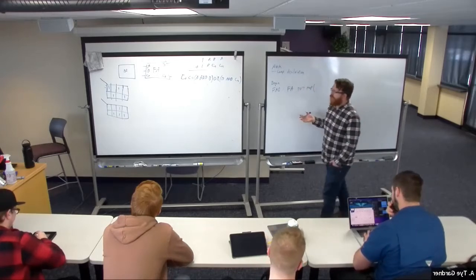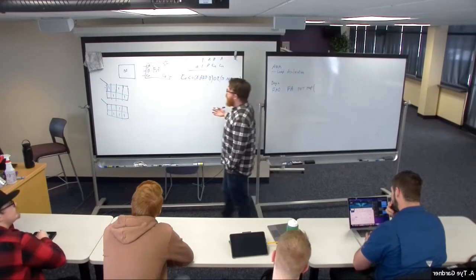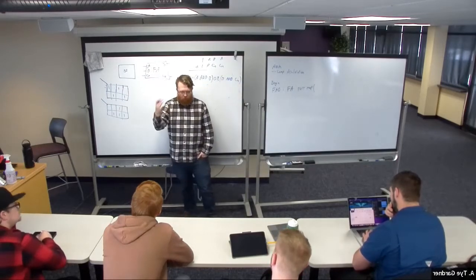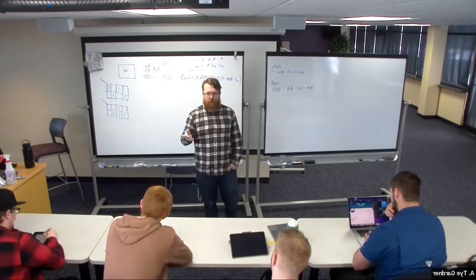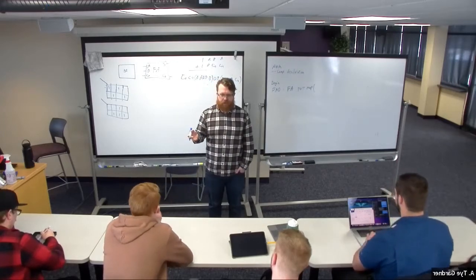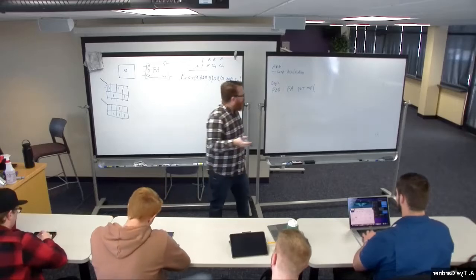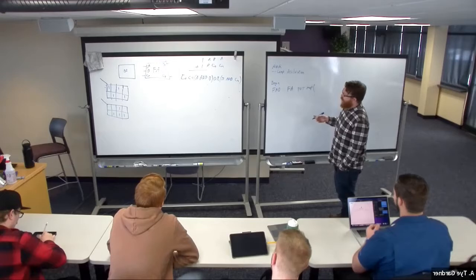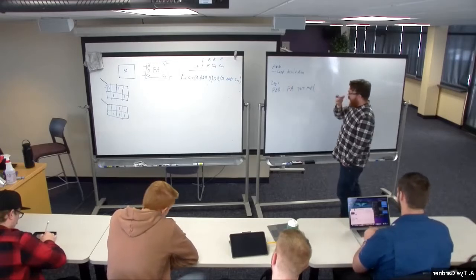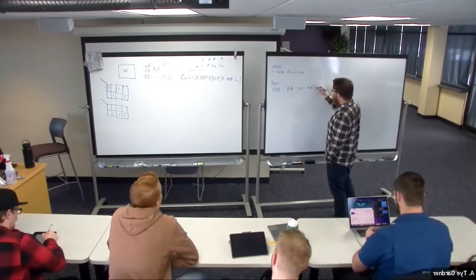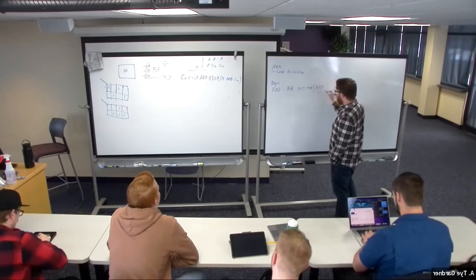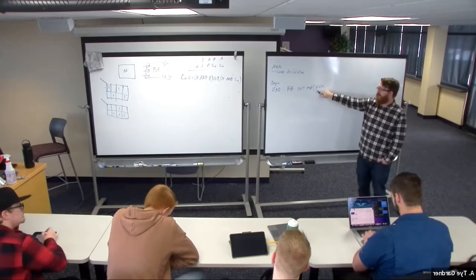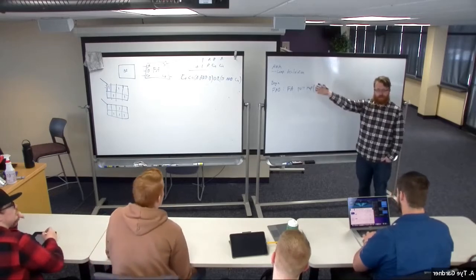The port map is just saying, well, my component declaration has told me that there's A, B, C in, S, and CO. It's told me what ports there are. Now I need to name the signals that are attached to it, right? Well, let's suppose that in my declaration, I have that full adder. And so I'm going to have A gets mapped to something, right? So this is just the reverse. This is how I say it. A gets mapped to something.